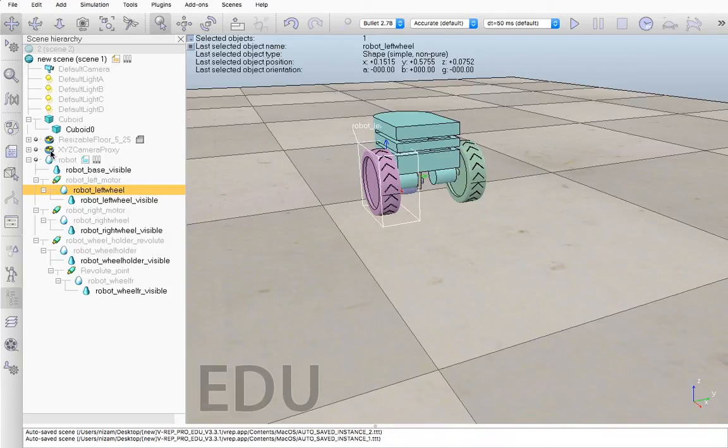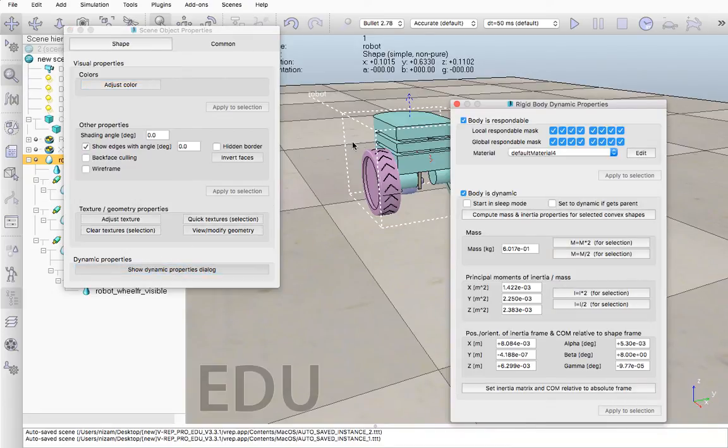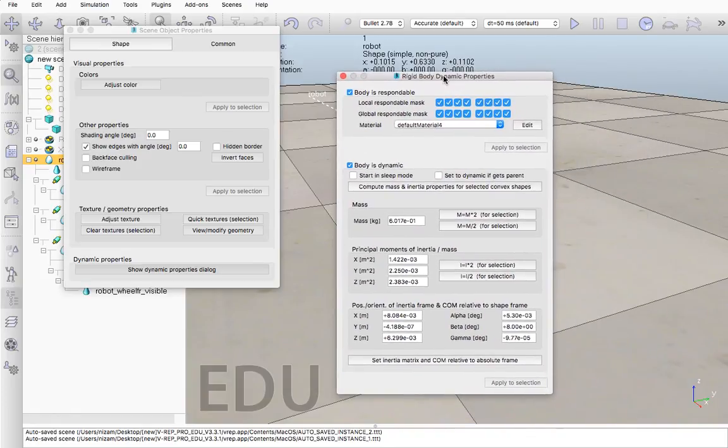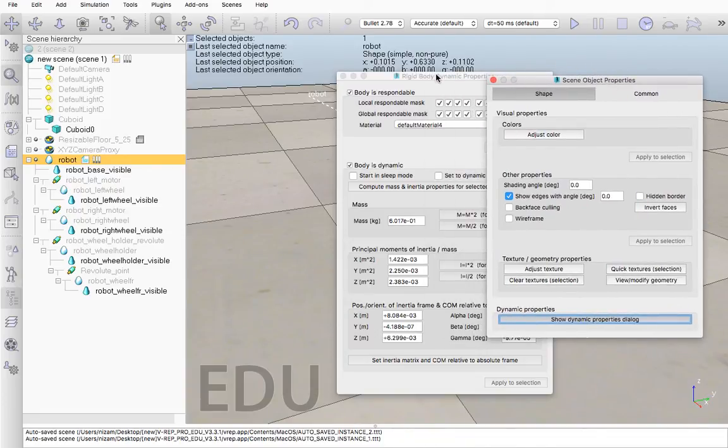Before going into path planning, we will see about local masking and global masking in the dynamic properties dialog box. In the dynamic properties dialog box, all the local masks and global masks are ticked. But in IK or any other dynamic model, we have to select alternate four square tick marks so that all the bodies are in alignment and the simulation will be smooth, or else the robot gets dismantled and there will be collision between the convex shapes.